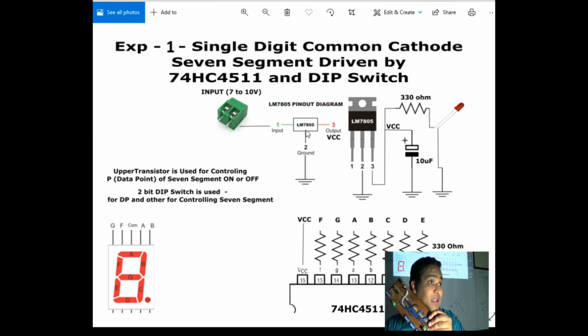You will just have to make some jumper wires over there. So in our PCB, since we are working over our design, I am only going to use one block connector over there. One pin will be VCC or the input, the other pin would be the ground.